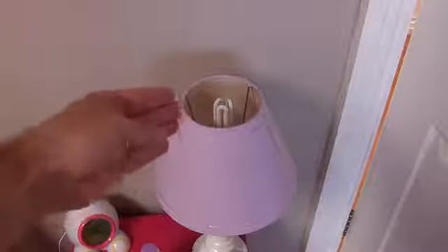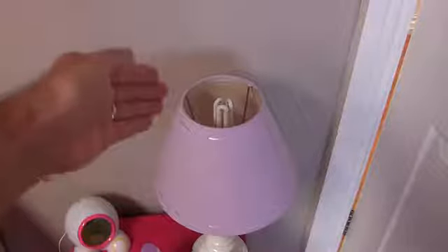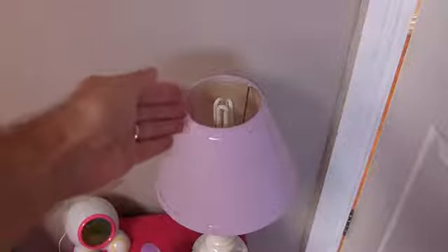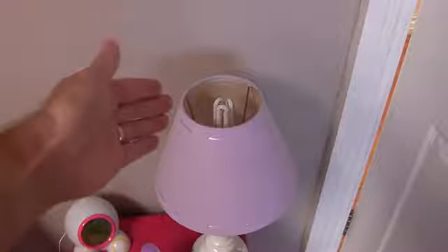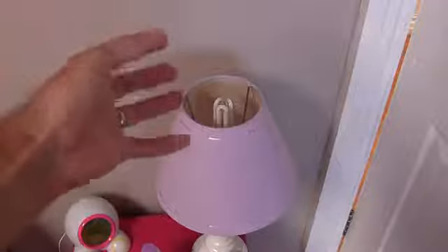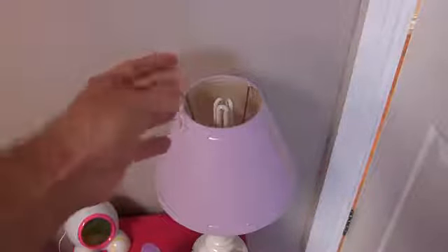Again, things like bedside lights, one serious consideration is the CFL globes. You might have a standard 60-watt incandescent globe in there, and you can easily replace it with an 11-watt or even lower wattage CFL. The colors are getting better, so you can get far better warm whites, replacing the type of light warmth that comes from an incandescent globe. And also they're almost instantly on, in that they don't need time to warm up. But those are things to consider.